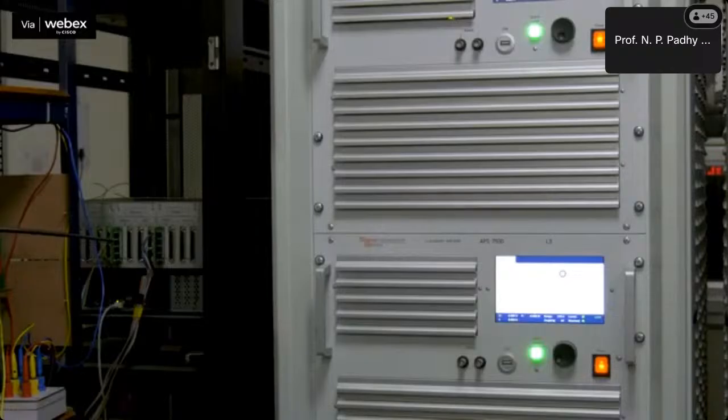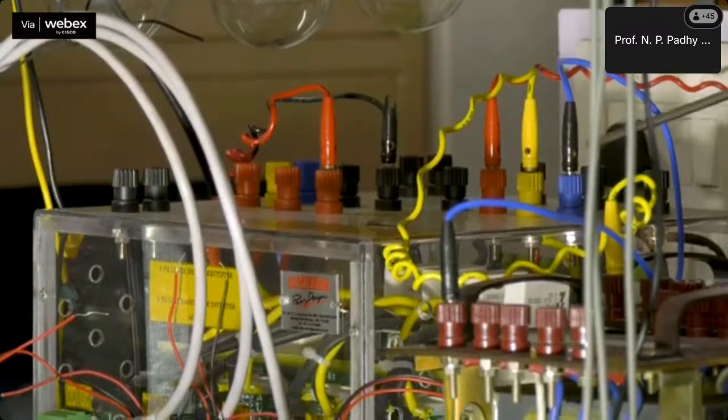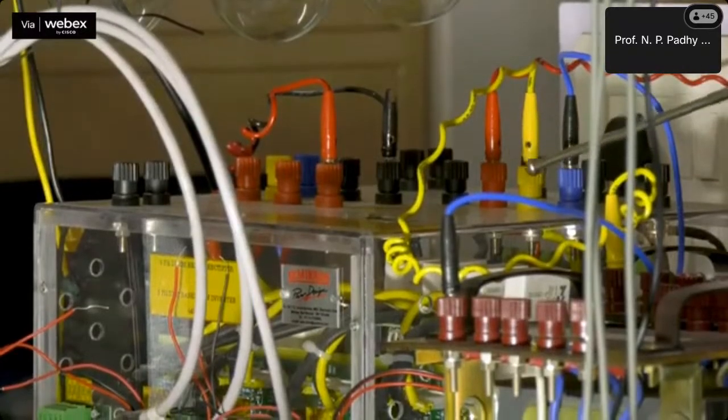This hardware setup is developed by interconnecting various components such as grid emulator, DC bus emulator, DC load, Semikron converter stack, filters and AC loads. The DC bus is emulated through a power amplifier and is connected to the DC side of the Semikron converter stack. The AC side of the Semikron converter stack is connected to the grid emulator through the filter with the help of a miniature circuit breaker, so-called MCB.